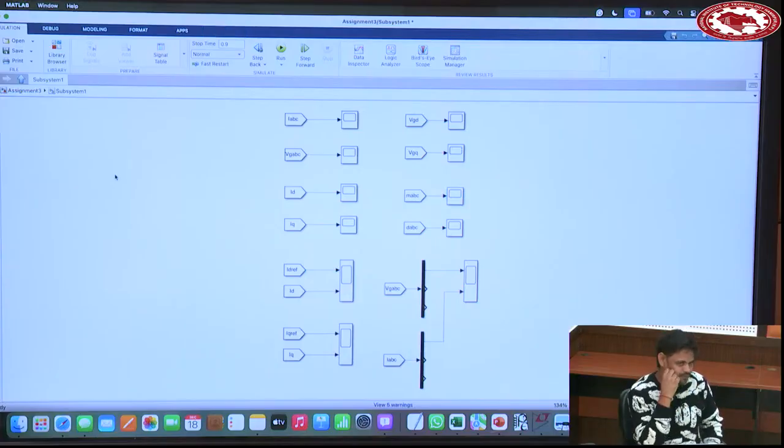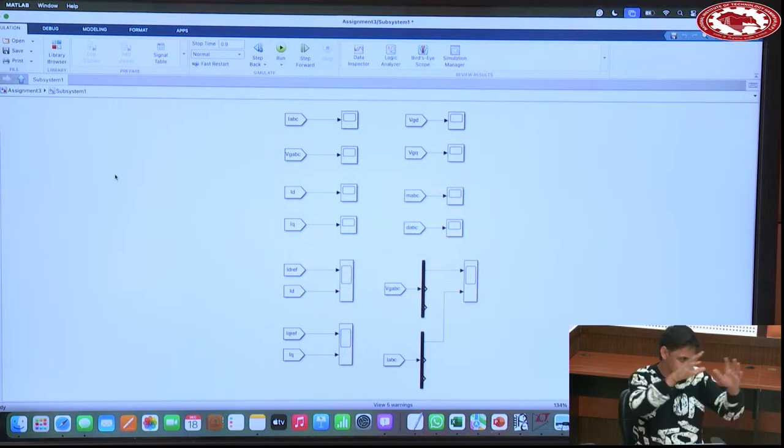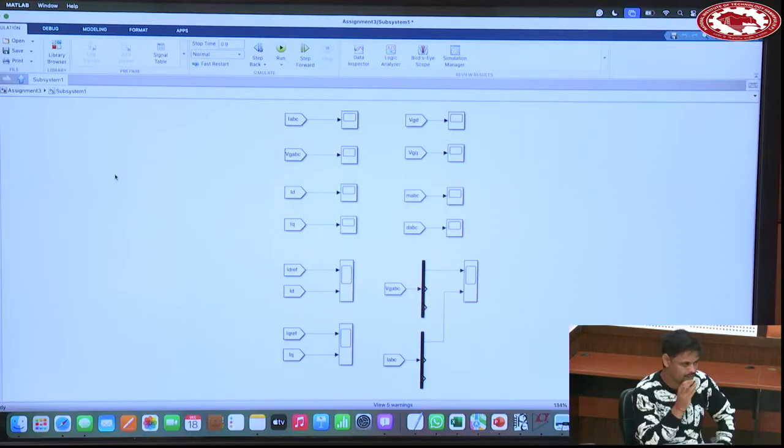The very first reason is your controller is not tuned perfectly. Your model, the control model you have made, you have made some mistake in the mathematical modeling itself, the control structure which you have made is not proper. Second, your compensator parameters are not good. And third, if both are correct, then you have loaded your inverter beyond its capacity, or you have chosen the DC link to be very small compared to the grid voltage.